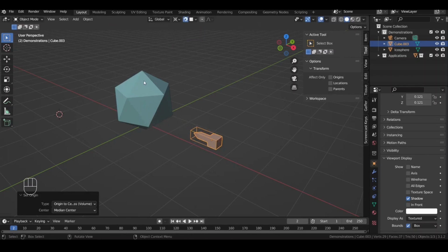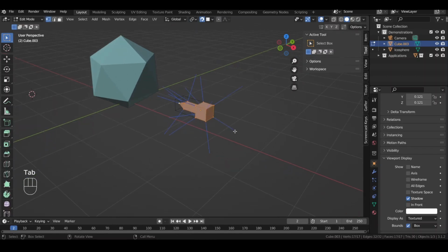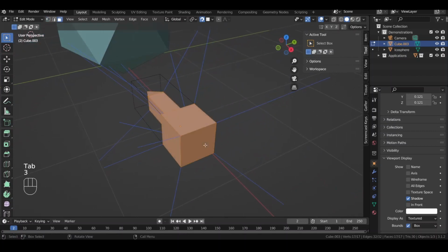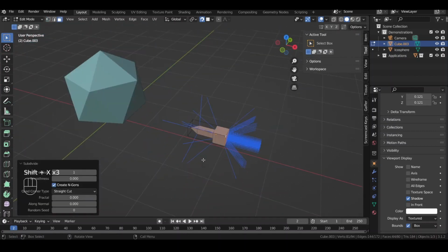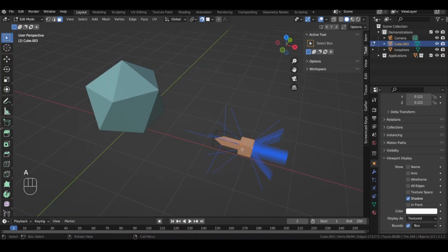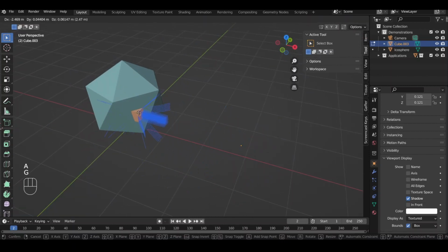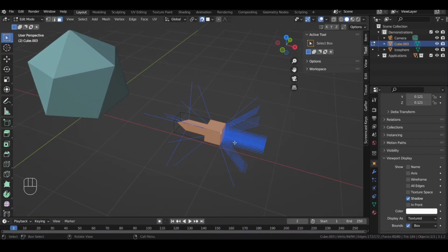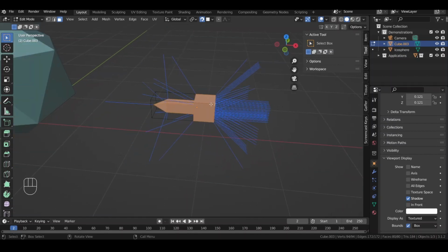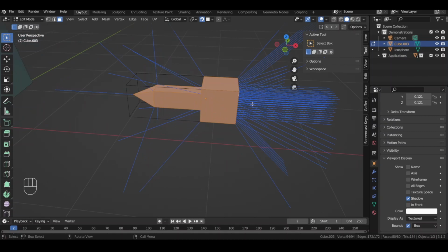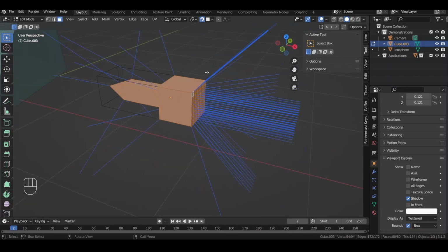However, it gets interesting when you're in edit mode, right? And so let's, for example, take this face and subdivide it a whole lot, right? And when you try to take this mesh and snap it onto the face, you can see what happens. It uses the median point of the mesh, right? Or of your object. And how I like to imagine it is that if you could take all of these vertices and you can find the middle, right?